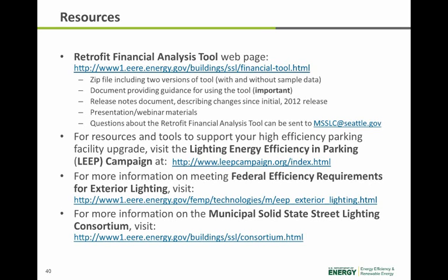Very quickly, for a product that uses a ballast, the way that you calculate LER, or luminaire efficacy rating, is the luminaire efficiency, which would come from a photometric report, times the total lamp lumens, so the nominal lumens from the lamp sources, times a ballast factor, which again depends on the technology, divided by the input wattage. That number gives you a luminaire efficacy rating.